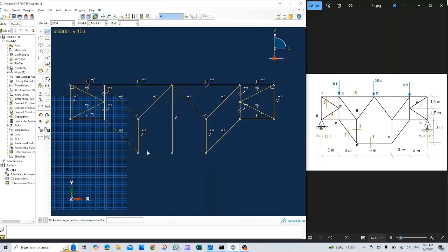We just add a line between D and E. Escape, and we go back to the delete icon to delete this extra member here and press done. Now we must connect CN. We have another line CN here. We use 2 clicks between the points. Escape. Activate the line again and have the corresponding line on the right part, and escape.